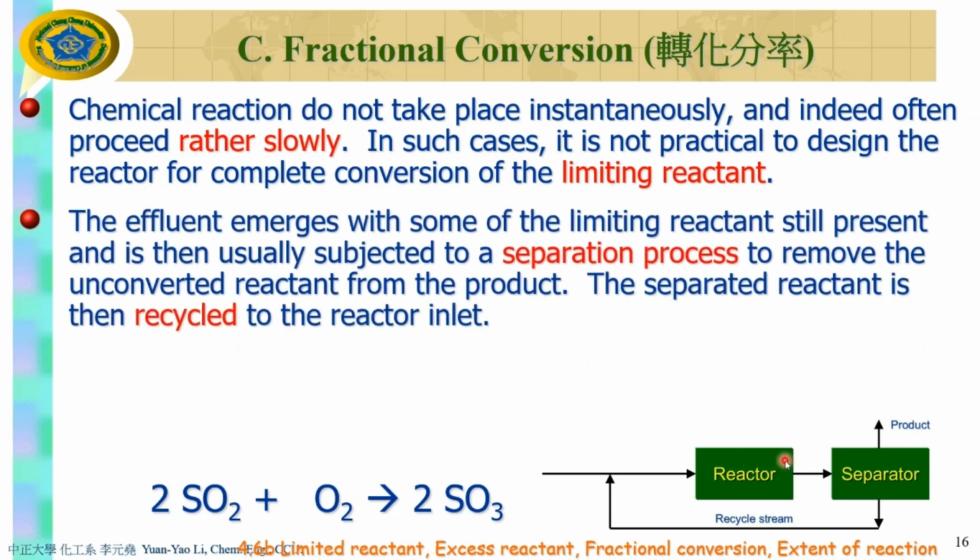So the effluent emerges with some of the limited reactant still present and is usually subjected to a separation process, this one right here, to remove the unconverted reactants from the product. The separated reactant is then recycled to the reactor inlet. That's what we learned on Monday, right?